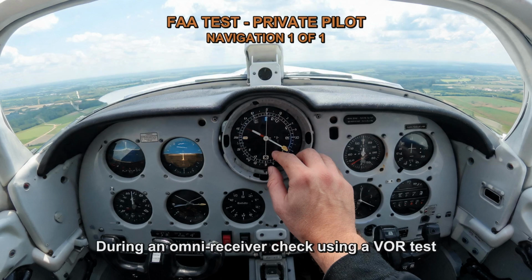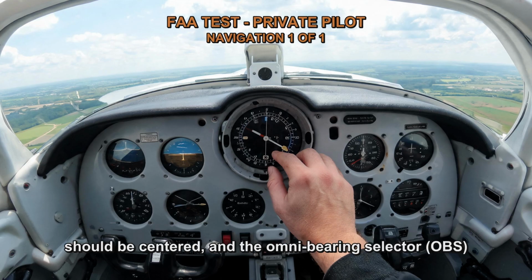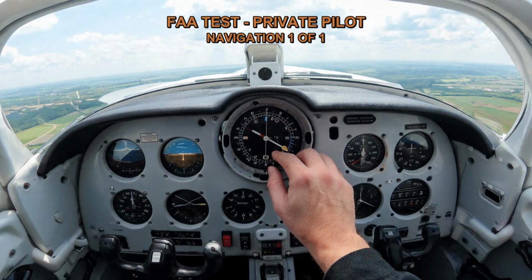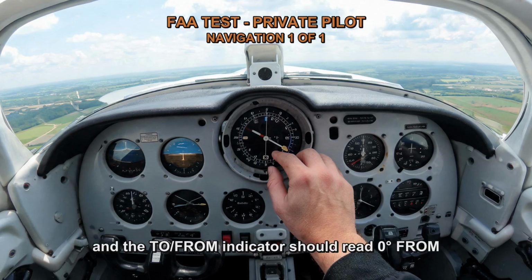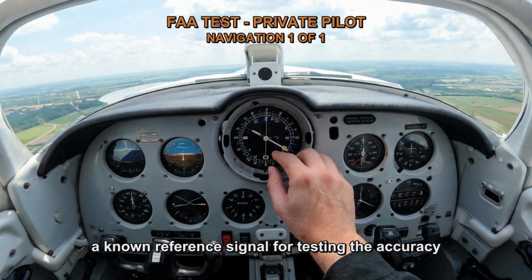During an omni-receiver check using a VOR test signal, VOT, the course deviation indicator, CDI, needle should be centered, and the omni-bearing selector, OBS, and the TO/FROM indicator should read 0 degrees FROM or 180 degrees TO, regardless of the pilot's position from the VOT. The purpose of the VOT is to provide a known reference signal for testing the accuracy of the VOR receiver.